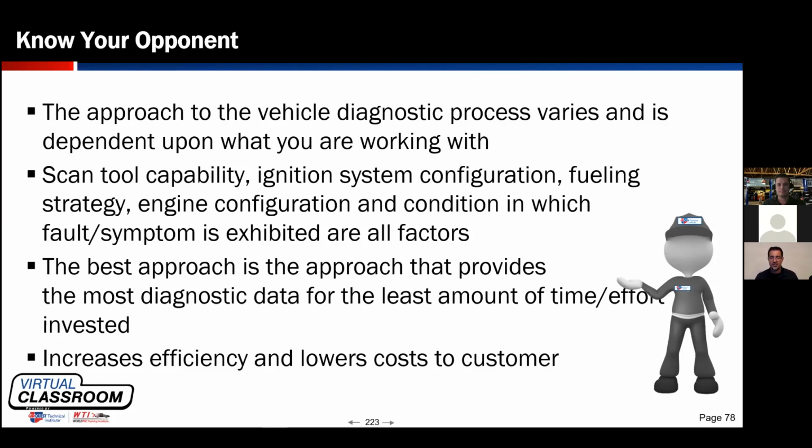How many cars do not support a Schrader valve, easy access to the fuel rail, right? Some of them don't even have pressure sensors where you can get usable data from a scan tool. So doing a fuel pressure test on one car might be a couple of seconds to perform, but on another car, it might not be even possible. It wouldn't make sense to do it.